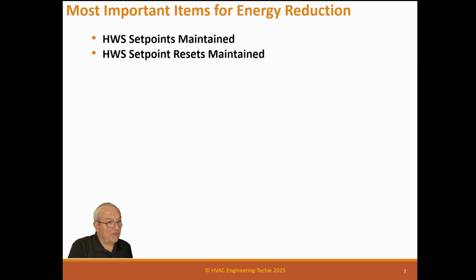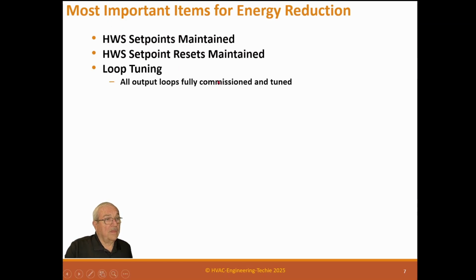So there's a couple of easy ones that an operator is going to do to normally fix something. That's one, blow out a schedule. "We'll let it run all night, and it'll be ready for you in the morning, I guarantee." Or two, well, it's that reset schedule. "We'll just blow that reset schedule out of there, and you will be 74 all the time. It won't set up and down." That's a problem, because it will blow out your energy efficiency also.